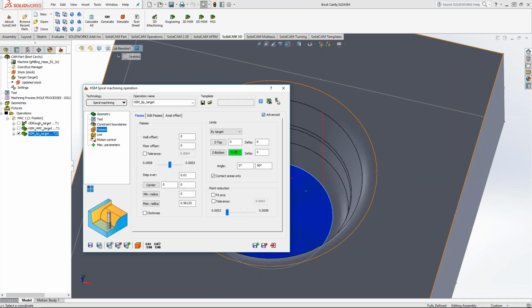So that's the main reason I use the ball nose, and I did that not just for these circular flat surfaces, but for a lot of other surfaces that were part of the surface of the part that was going to be molded, that was cosmetic, where people were going to see it.